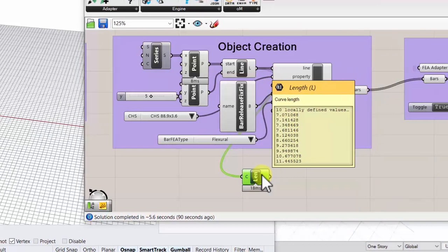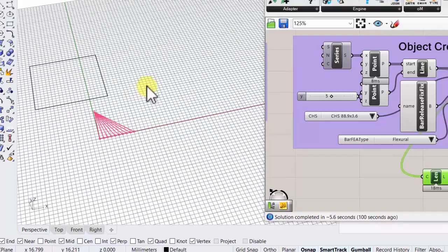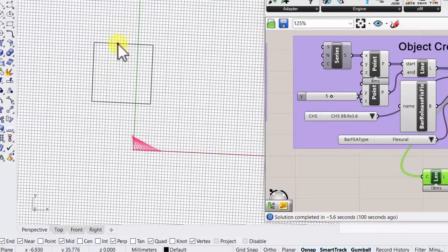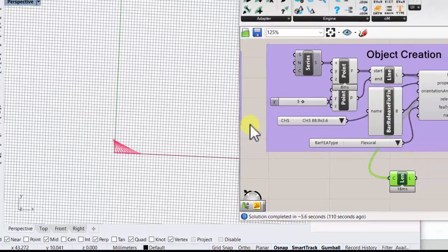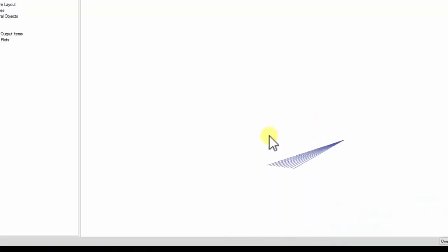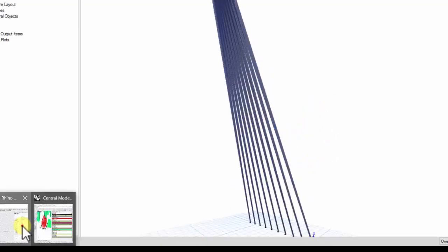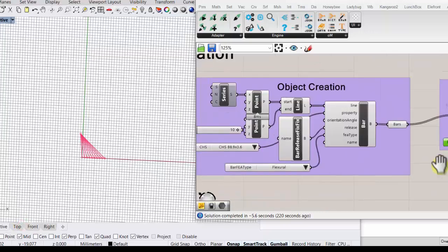But make no mistake, if I came out here and actually drew something thinking I was drawing something 20 meters by 20 meters, or 2,000 by 2,000 or something, no matter what you do, BHoM will interpret it as meters, newtons, pascals, right? So there's no gigapascals, there's no giga, mega, kilo. It's all straight up base units, and it's all SI. So guys, for a structural engineer looking to get involved here, that's the 80% rules right there that'll get you going.